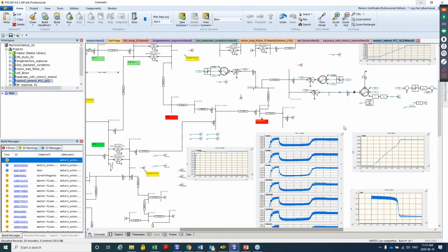Every time you start the motor, remember, when the motor speeds up, the slip is high, and it will draw a large starting current. The large starting current is not of concern for the motor, but these are weak grid locations. These motor pumping stations are at weak locations further from the main transmission grid.